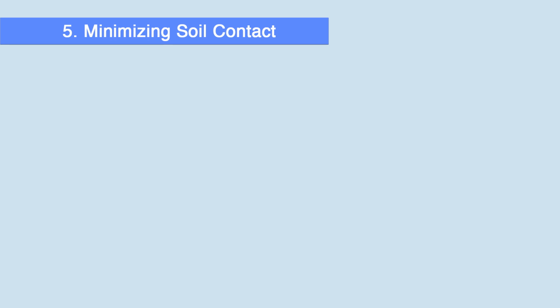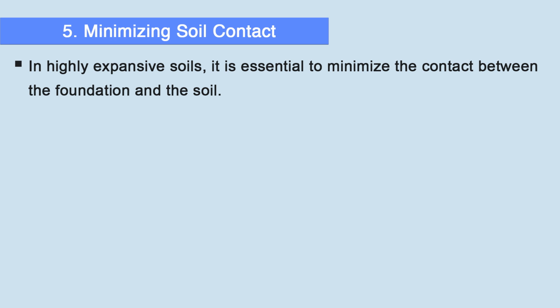Then the next is minimizing soil contact. In highly expansive soils, it is essential to minimize the contact between the foundation and the soil.